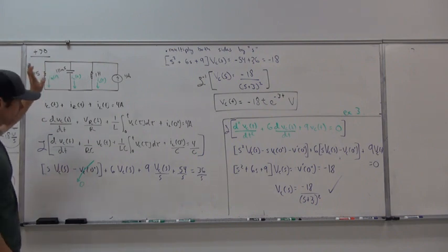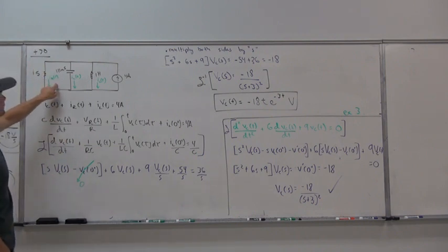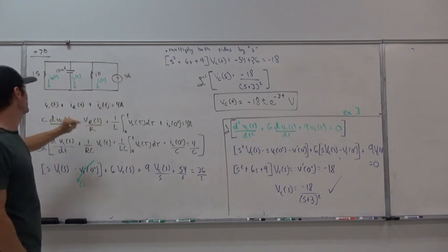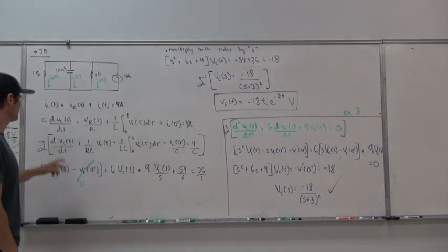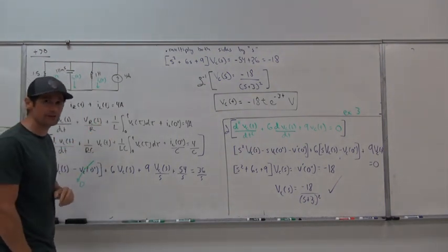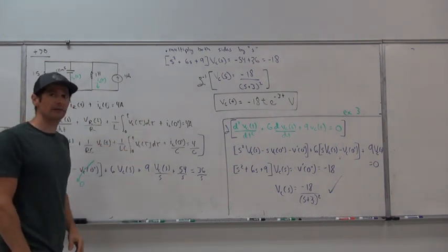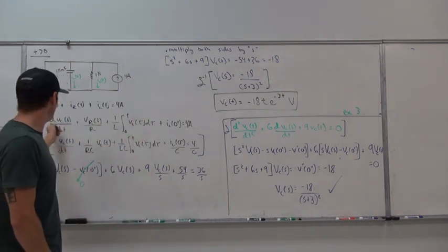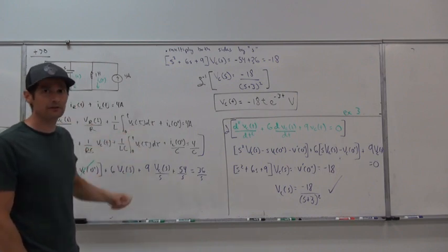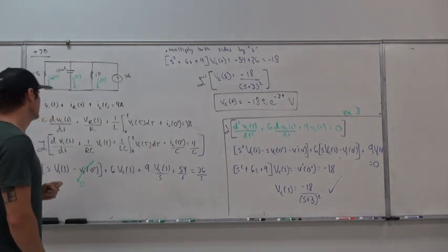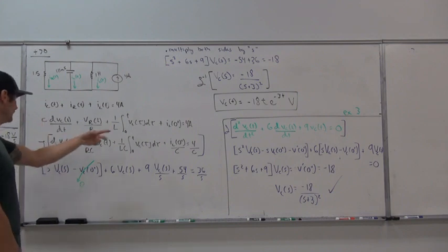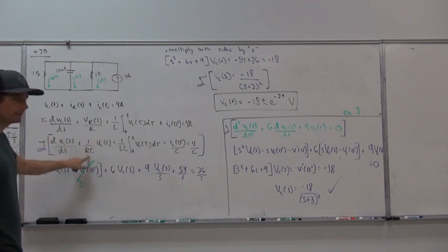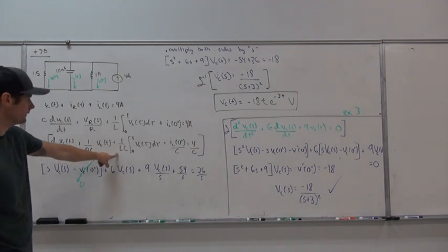Let's develop this differential equation, then let's solve the sucker. So IR of t, IC of t, and IL of t. IC of t plus IR of t plus IL of t is equal to 4 amps. So guys, once we expand this by those current-voltage characteristics, the whole equation is already in terms of the voltage that we want, because Vc of t is equal to VR of t, and that's equal to VL of t. And if we put this into a standard form by dividing through by c, notice right here we got that coefficient of 1 over RC and also of 1 over LC.